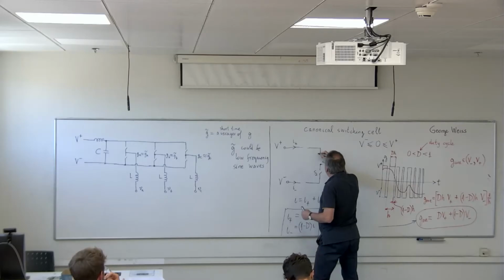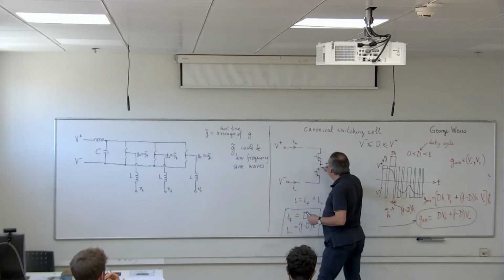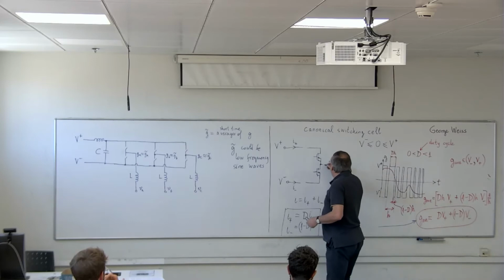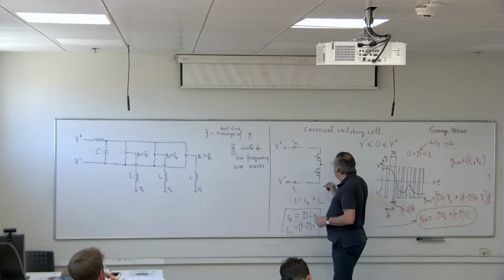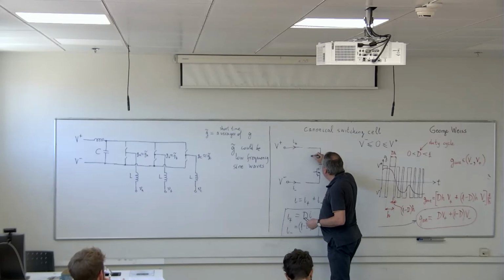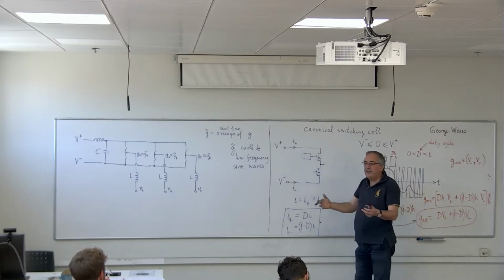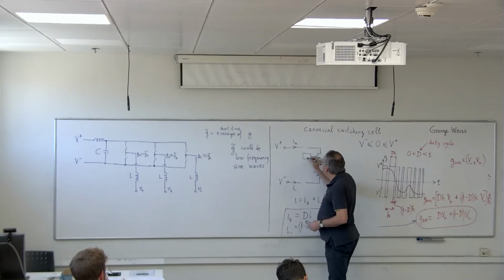This switch is typically, not necessarily, but typically, a MOSFET transistor. But it can be also something else. It can be, for example, an IGBT, which is a similar device. I mean, it's also a switching device, but more powerful and less fast. So what I have drawn now are two MOSFET transistors. And these MOSFET transistors are connected to a circuit which you buy ready-made. It is a complicated circuit, which is a so-called driver.